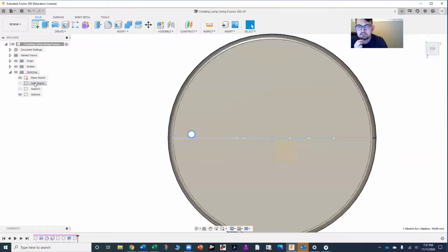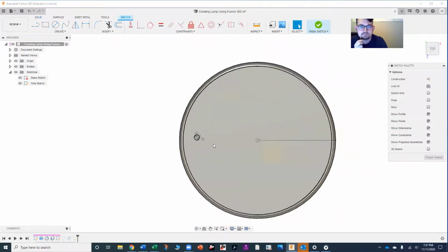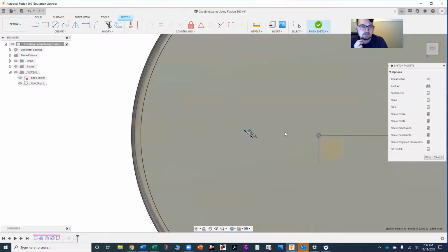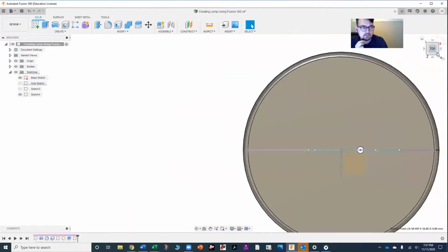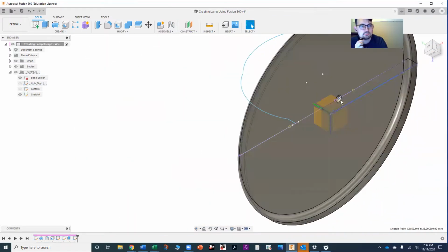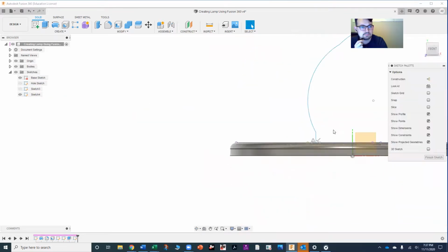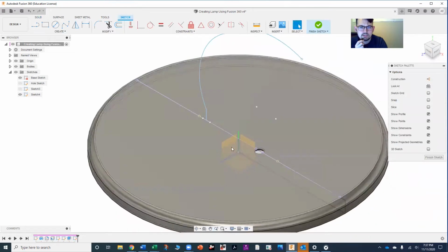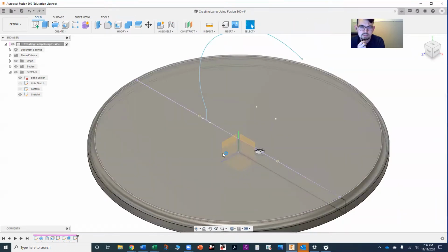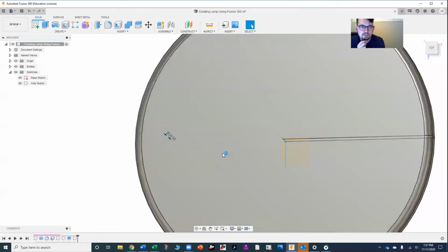Let me do that hole sketch one more time. If I move this hole sketch over here, somewhere along the center line here, I hit finish. As long as I'm in that same plane as the sketch, my arm should follow within reason. I don't know why it's not following, but typically it does. Oh, you can see the geometry there, but those haven't locked down correctly. Anyways, okay, Control Z, and I'll undo all of that and go back, but that's the basics.